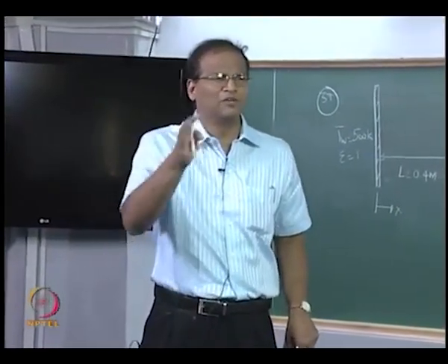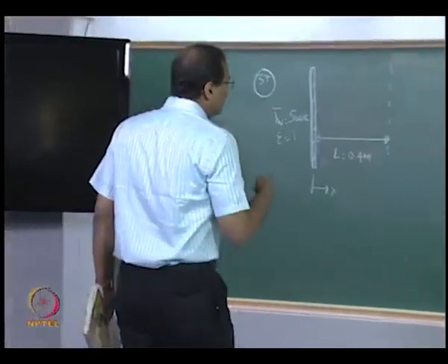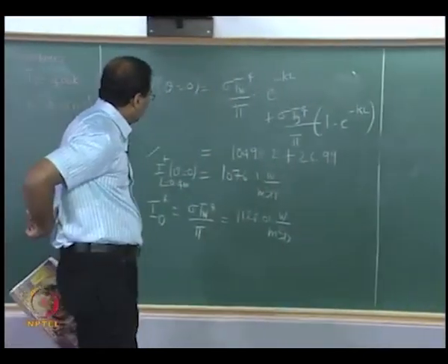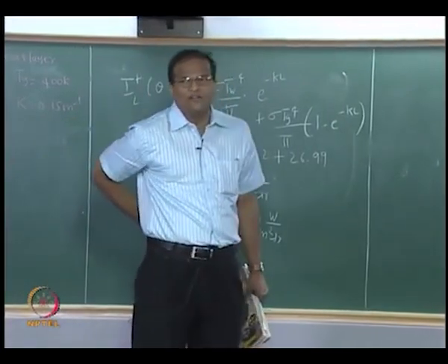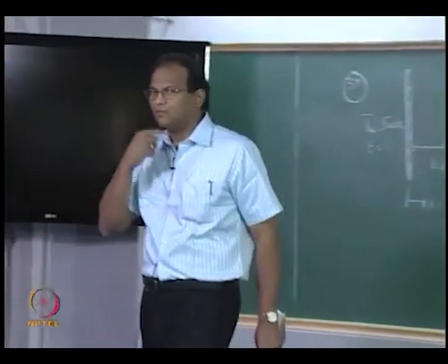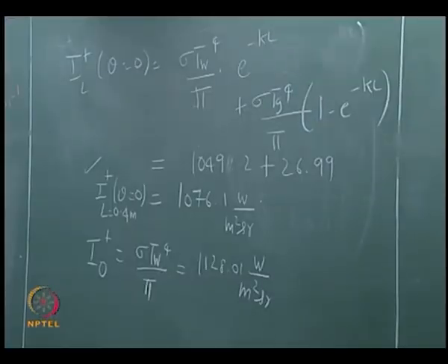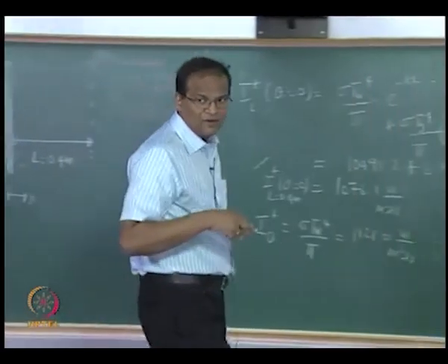Just blindly you can substitute the formula and get the result. But if I at L divided by I naught is 0.5 or 0.6, then it is a very questionable assumption. But we have not made any assumption so far. The optically thin gas assumption will come when you are using that in the Q.